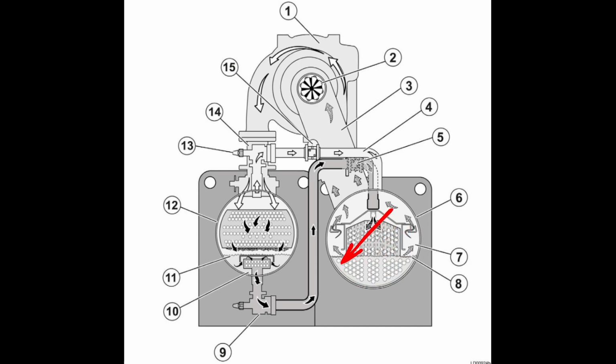But as the refrigerant begins to stack higher and higher in the evaporator, then we need to have that recovery line adjusted accordingly. We don't want to risk being over that refrigerant level, but we want to be just under the top side of it so that we are getting that mixture that we're looking for.